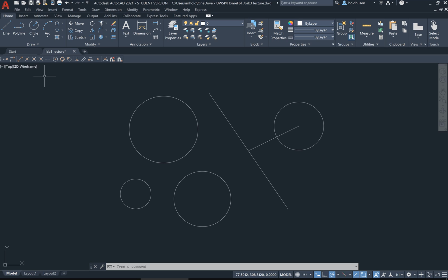Okay. And there's lots of snapping. Some of the auto snap is already part of this, but there are certain things, for example, snap to perpendicular, which is right here. Let me show you how to do that, where it might not be obvious. And these snaps only occur generally when you're in a line function. I couldn't snap to something when I'm just selecting it. But if I go to line here and start drawing a line, I could auto snap to the end point there. Or I could come over here and force it to say, I want a perpendicular to that line. And when it snaps, I now have a 90-degree angle, and it's snapping just to that line.